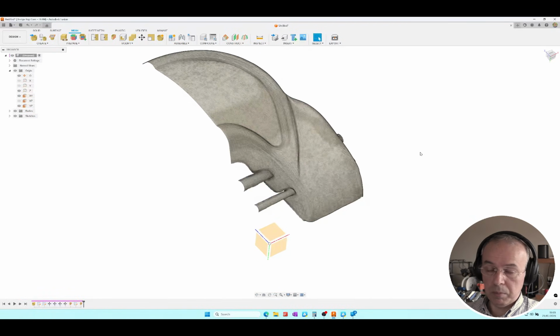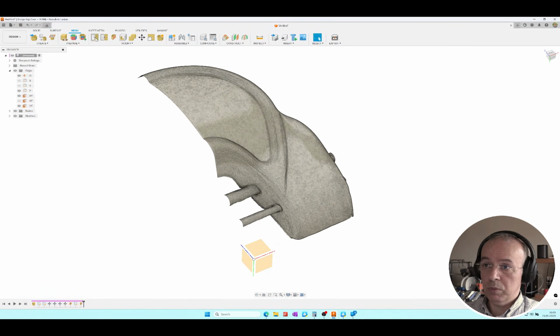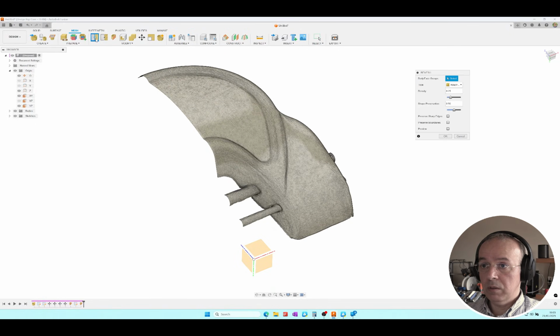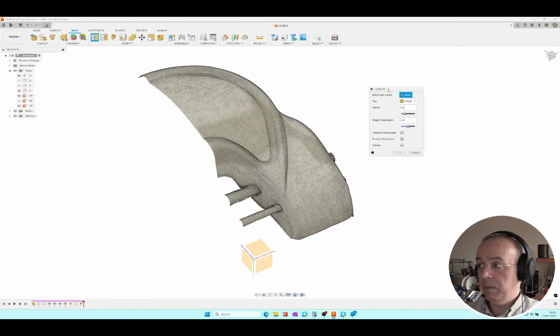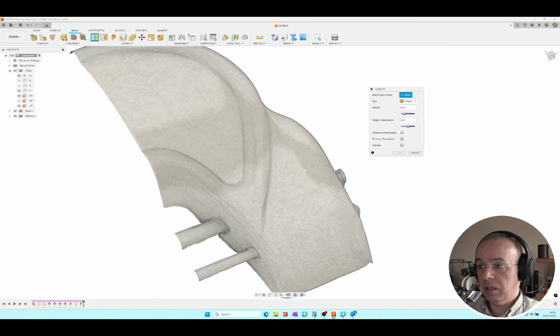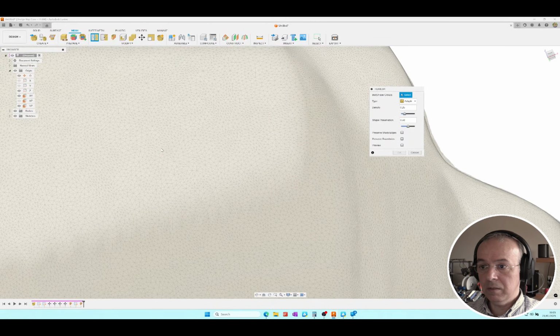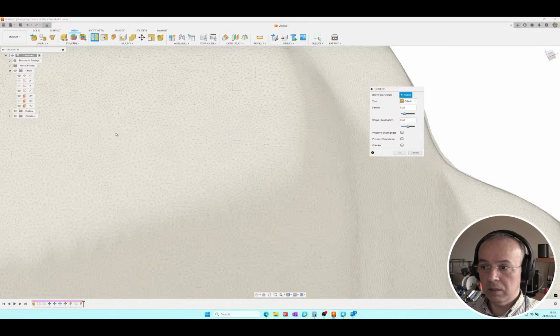I'm going to do something that might be necessary, okay? There's the option to use remesh or reduce. I usually use reduce, which reduces the number of elements. However, remesh essentially transforms the mesh. Take a look at the current mesh. It has areas with different element sizes. You can see there are slightly larger and smaller elements.